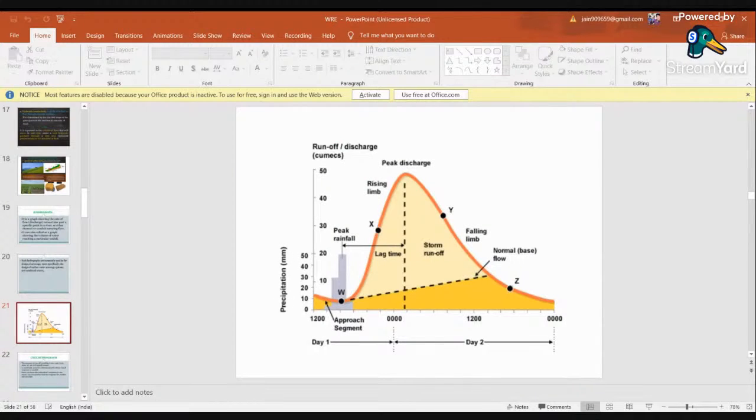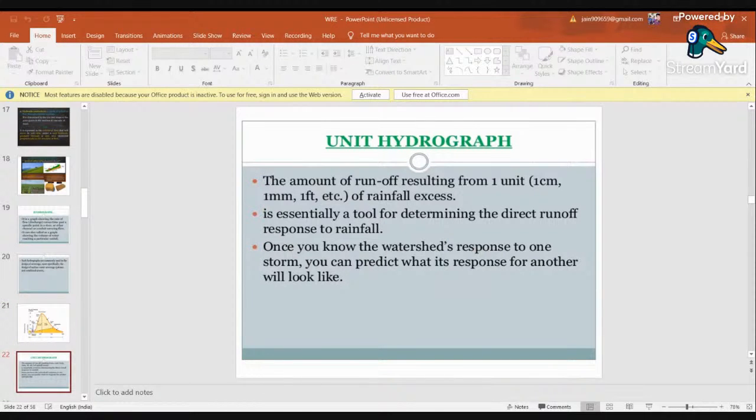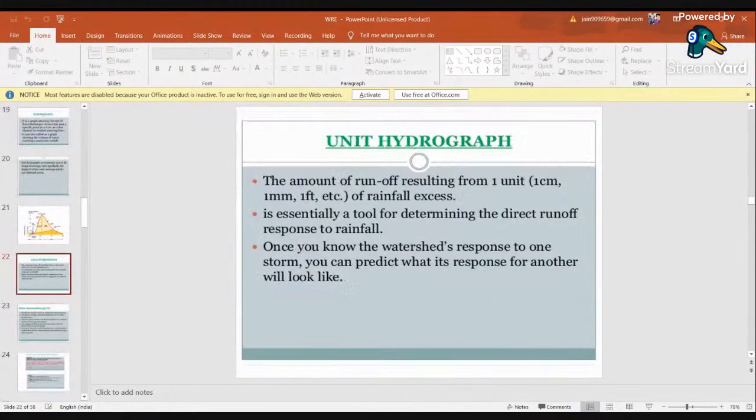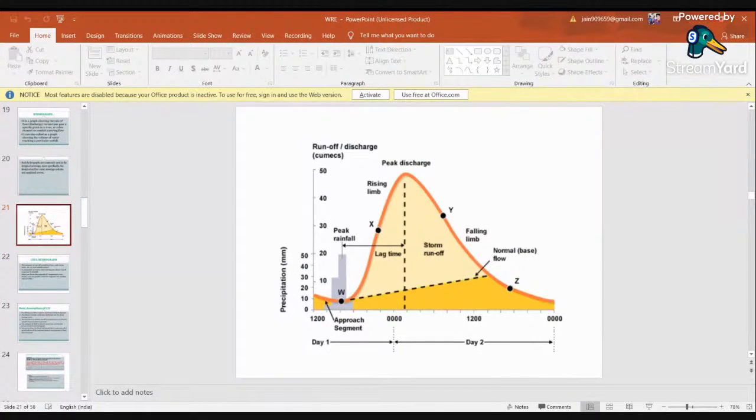Now, there are several types of hydrograph. One is your natural hydrograph, then unit hydrograph, then dimensional hydrograph, synthetic hydrograph, dam hydrograph, etc. Out of which the unit hydrograph has more importance. The first one is your natural hydrograph. Natural hydrographs are ones recorded at a stream gauging site, and are a fingerprint of the upstream drainage area. Then there is the unit hydrograph, which is of our use.